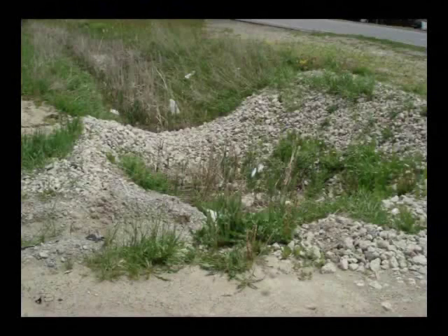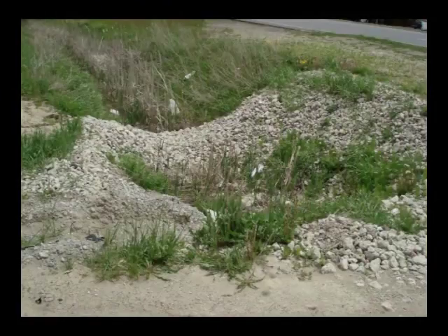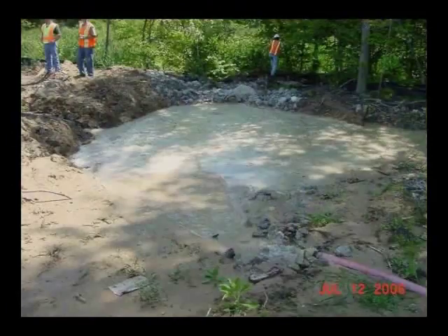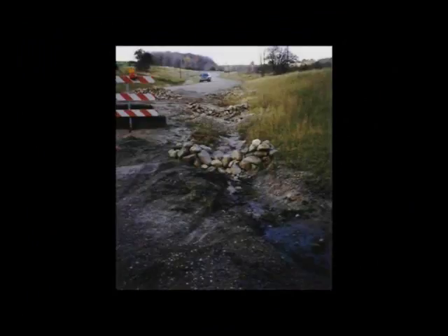The primary purpose of check dams as an erosion control is to reduce water flow to non-erosive velocities in ditches, diversions, or other areas of concentrated flows. Check dams can also function as sediment controls if runoff is slowed sufficiently to allow large-sized particles to settle out of the water and be deposited upstream of the check dam. The deposition of sediment can be increased by excavating sumps upstream of the check dams. Check dams are generally constructed of rock.